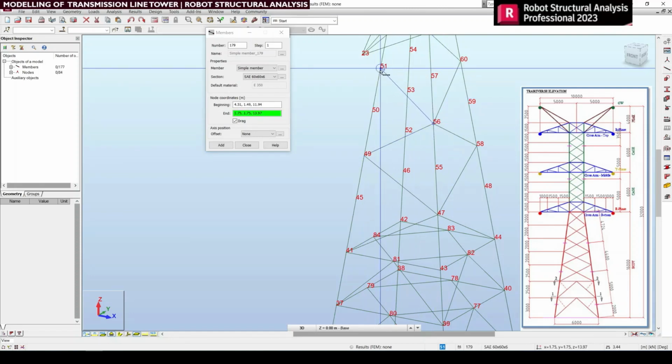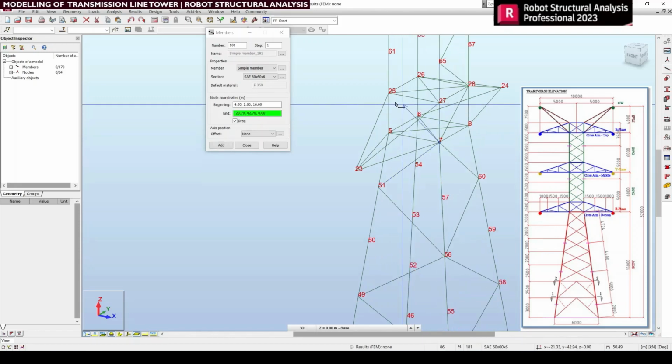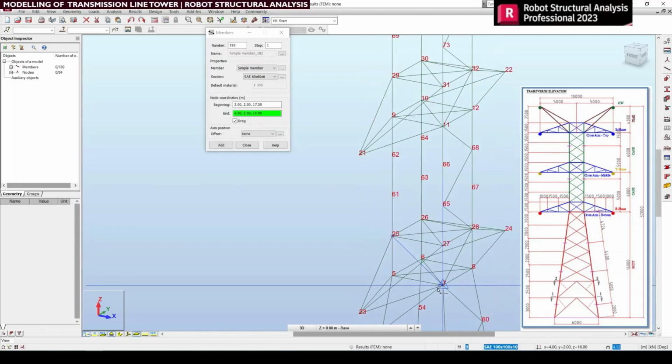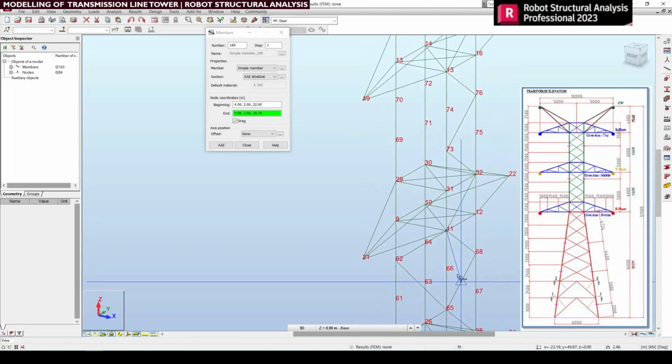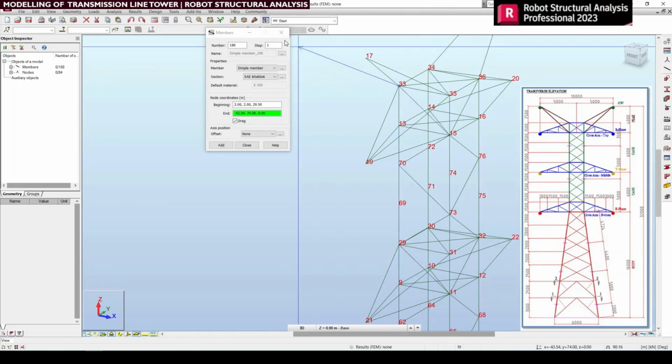If suppose the visual which we want to do it for bracing is not clear, we can do segregation or viewpoint separations. That we can do by selecting one point of view and creating a viewpoint. So let me explain that.